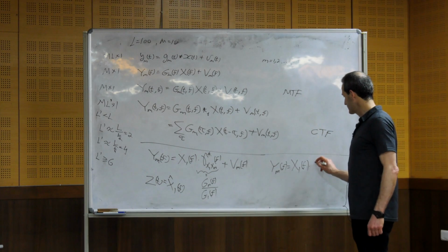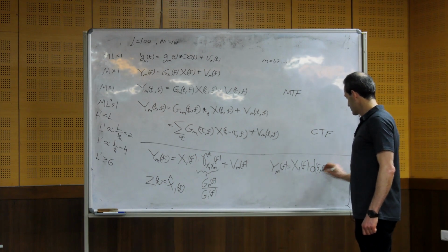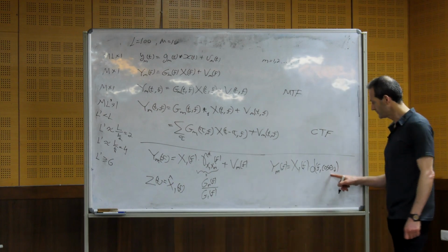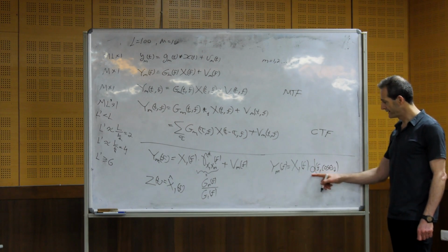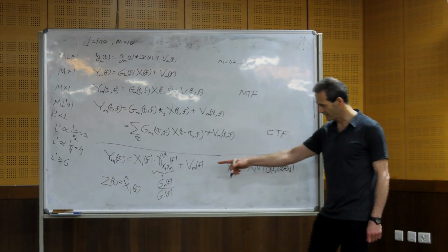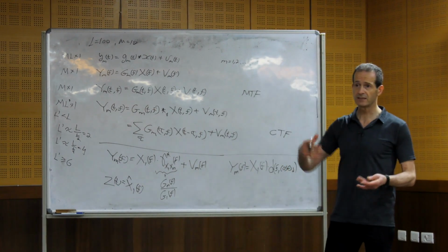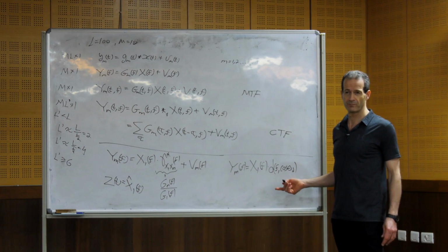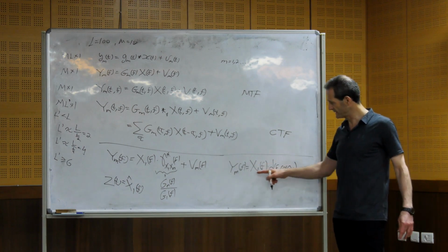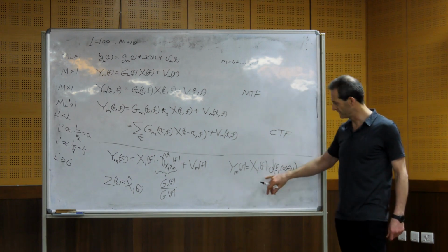So it can be written like this, d(f, cos θ_d). So θ_d will be the direction of the desired source, and this will be something similar to the relative transfer function when we don't have reflections. So it's just an exponent. It actually corresponds to delay. See, because if you have a sensor delay when you transform into the frequency domain, it's just a phase difference.